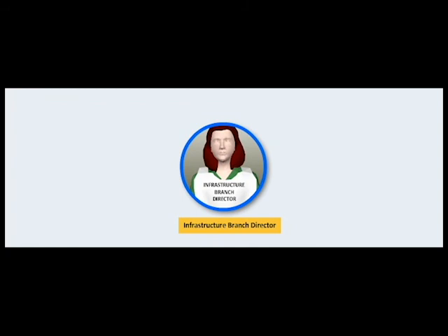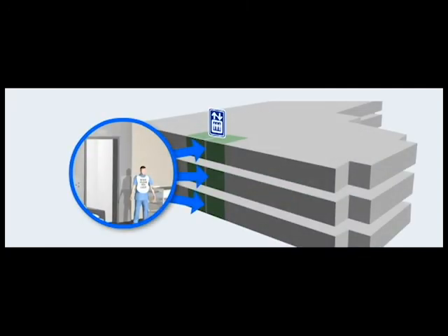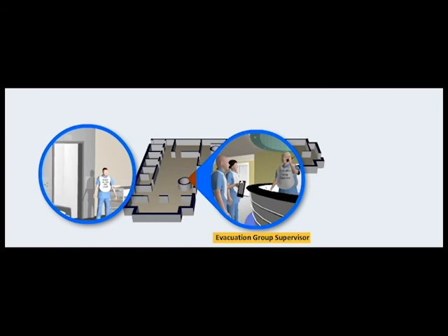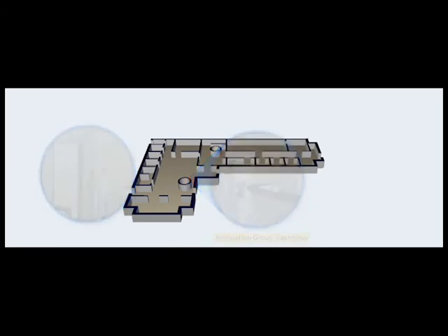The mission of the elevator control operation is to optimize vertical movement of critical resources and evacuees between floors. A lobby elevator controller should be established in each elevator lobby. As quickly as possible, any usable elevators that will support the evacuation should be staffed with engineering and maintenance personnel assigned as elevator operators. The lobby elevator controller becomes the coordination point between individual elevator car operators and the evacuation group supervisor. As an evacuation group prepares patients for movement, they coordinate with the lobby elevator controller to assign a car suitable for the load.